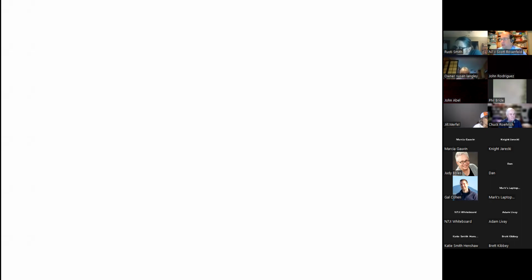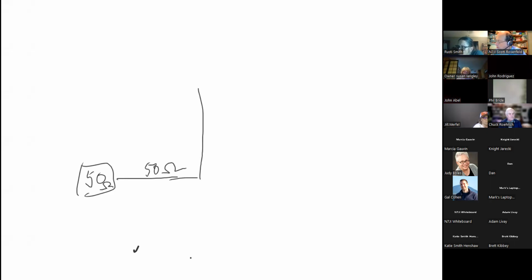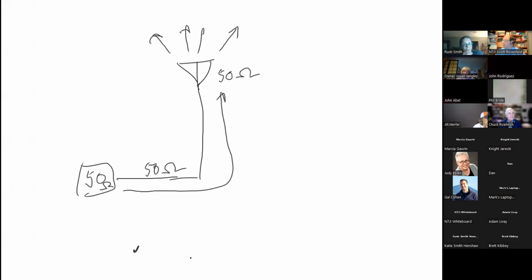Okay, so now what we're going to say is, what is an antenna? Ideally, if you have a 50 ohm transmitter and 50 ohm cable, which is a conduit to this load, that would be 50 ohms. That means that your signal goes out into the world and never comes back. Okay, so let's say that I'm testing something off the air. I want to still be able to transmit full power. I can replace that 50 ohm thing with a resistor, which is 50 ohms.